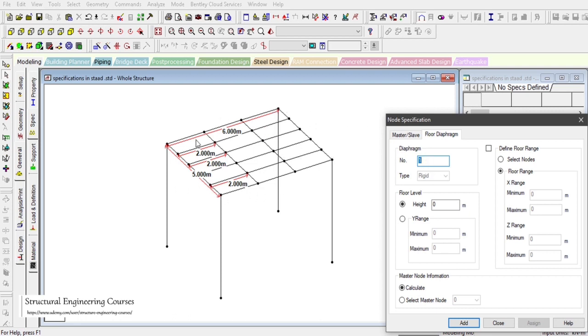Let us say this whole arrangement is the steel structure arrangement. On the top of it a deck slab shall be constructed. So we can model a composite deck slab here, but to simulate the effect of this composite deck system we need to put a diaphragm, or in whatever RCC structure we are modeling in STAAD Pro software, and we are doing the dynamic analysis.